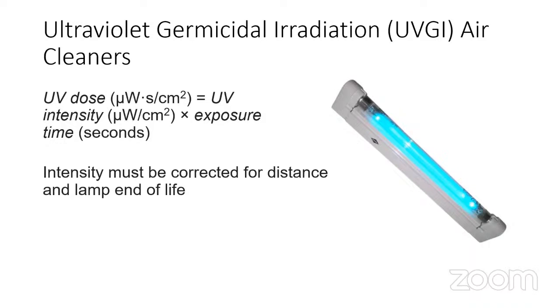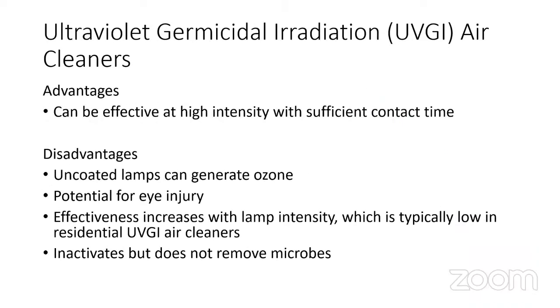Also the end of life of the lamp would be specified. That is where it is expected to reach 80% of its initial UV output. So this lamp life also is a factor which must be considered in calculating the intensity. Considering all these factors, suitable UV dose has to be decided, and the UV lamp has to be chosen for different applications.